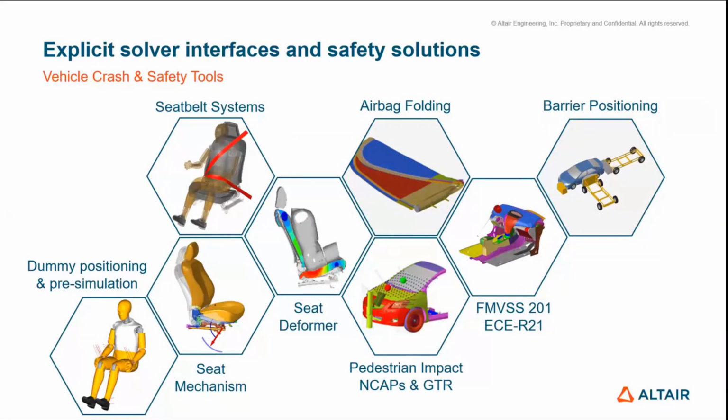For vehicle crash and safety, especially for the occupant safety analysis, here as well, we have today everything you need as tools available in HyperWorks, from dummy positioning with resimulations, seat mechanism to position the seats in the different positions, seatbelt system to create the complete seatbelt system with all the solver related features.